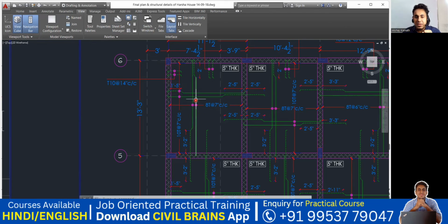That is this bar and this bar. The distance you are supposed to provide is an 8 diameter bar, and the distance between this and this bar is 7 inches center to center spacing. Similarly, this bar and this bar, what is the distance given? It is mentioned here. In this direction, these two bars, whatever they have given, you have to provide a 10 diameter bar at 7 inches center to center spacing.